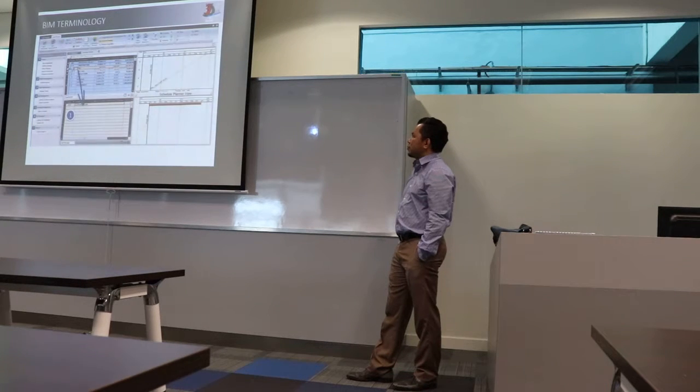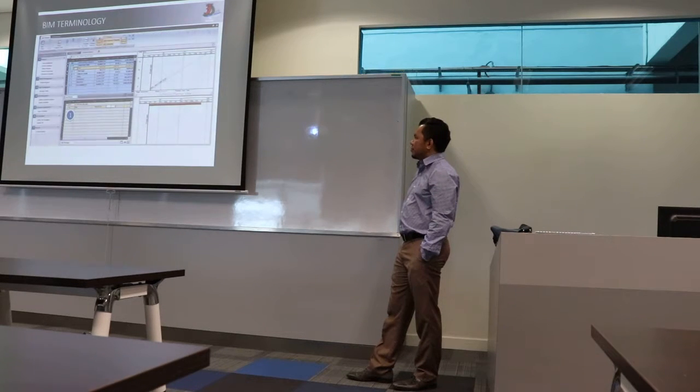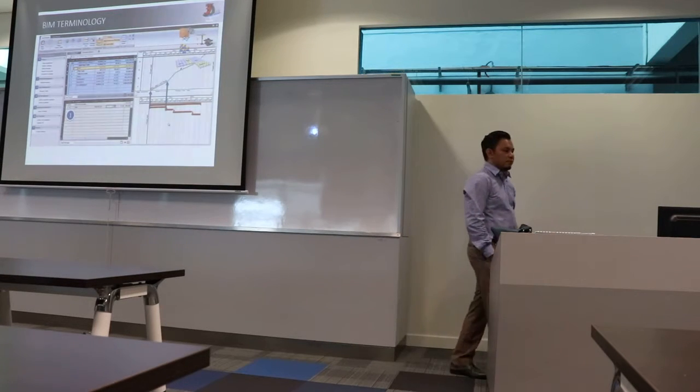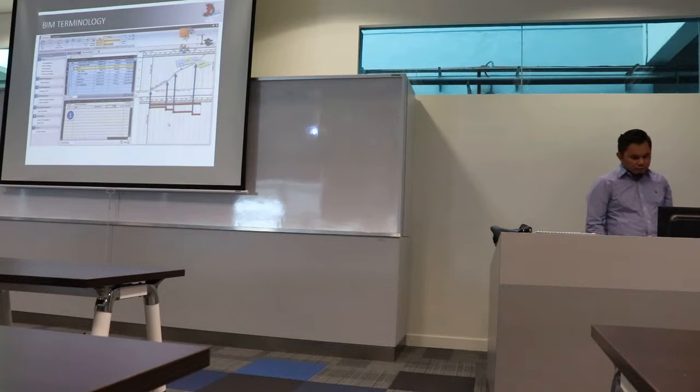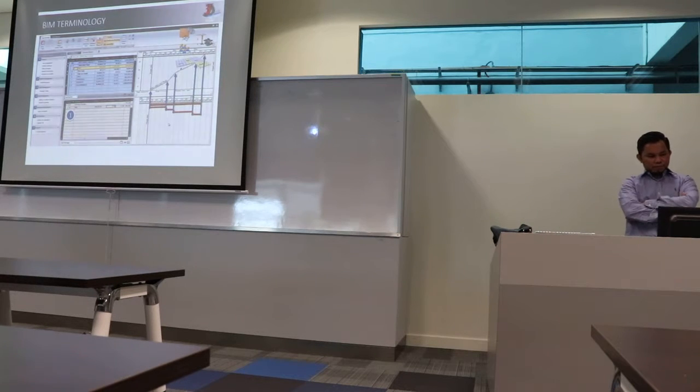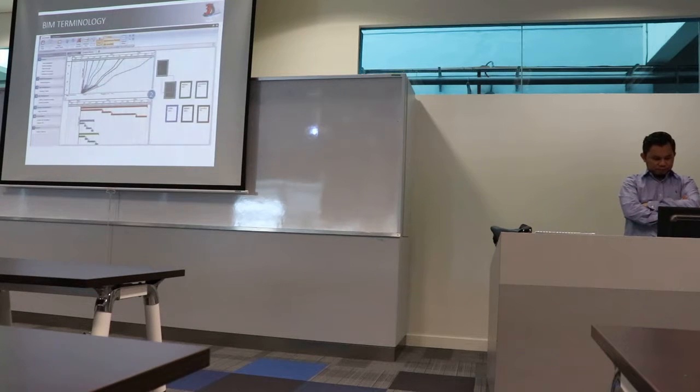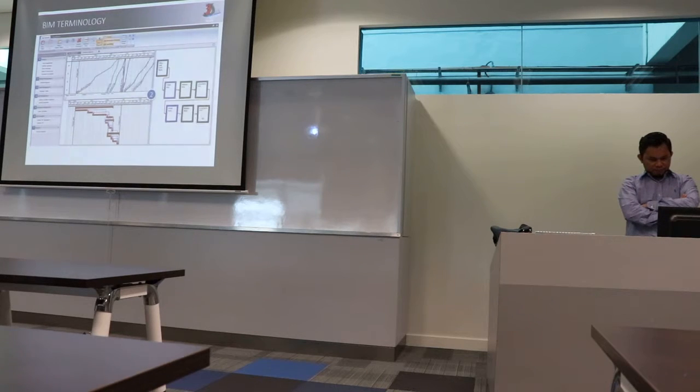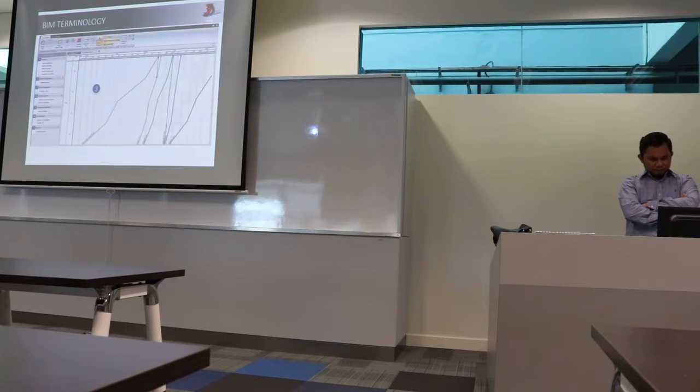The next step is to leverage our estimating quantities, costs, and any resource data to load the schedule. We drag and drop the cost line items into scheduled tasks and see how the quantities and productivity data now drive the schedule durations. The location-based quantities drive location-based tasks, which can be manipulated in both the flow line and the Gantt view. We define trade logic, which is automatically copied to all relevant locations, and balance the schedule around the bottleneck trades by simply dragging and dropping the lines.